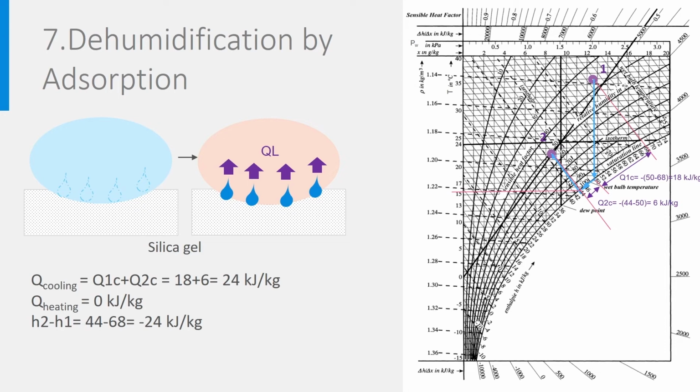Point of attention here is that at a certain moment the hygroscopic material is completely saturated with water and cannot absorb any humidity. The only way to cope with that is to dry the silica gel by heating it in such a way that water is expelled. Therefore, this works as a continuous cycle. The heating needed to dry the silica is approximately equal to the heat of vaporization of water and depends on the temperature at which the heating is done. So in the end, heating is still needed. Nothing is for free.